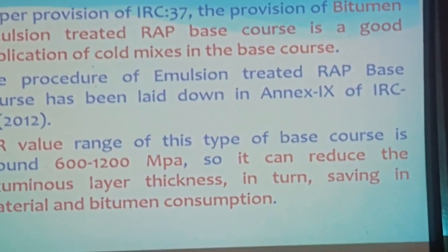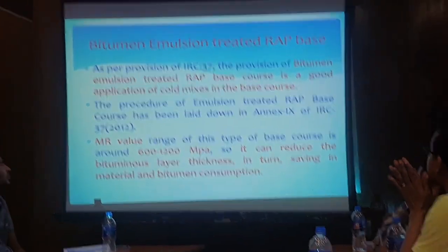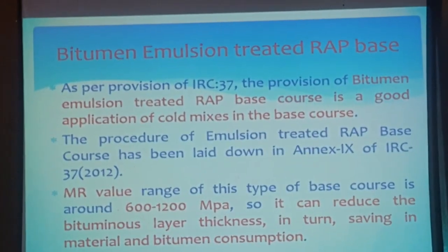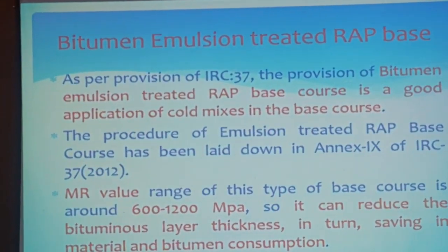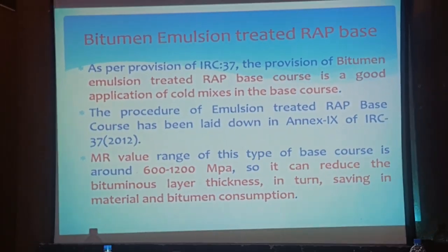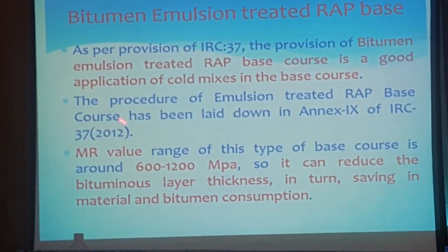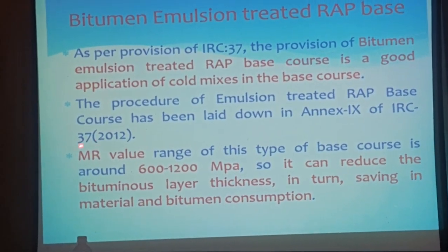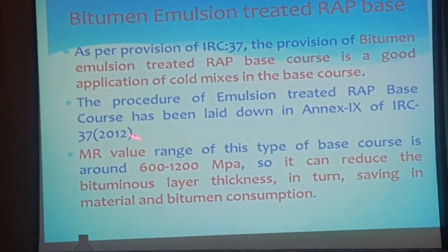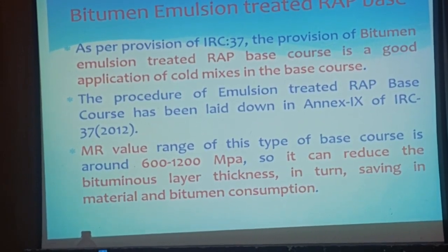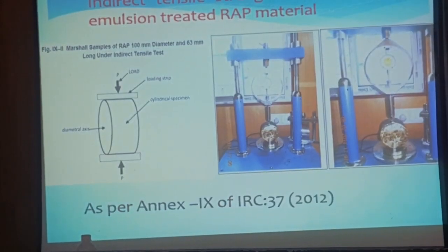And this is the RAP. RAP is your reclaimed asphalt pavement. In the IRC 37 2012 version, in Appendix 9 it was there. Now in the IRC 37 2018 version, it has been removed and it is reflected in IRC 120. This is there. I'll show you this also.